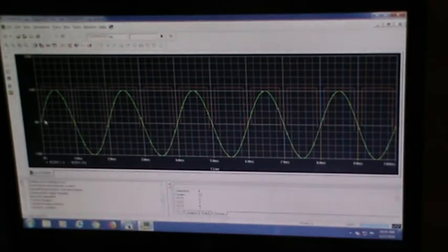See here, you are getting a square wave from +3 till here, more than 3 until less than 3. Till there you will be getting a square wave, and the rest all will be zeros. You will be getting a zero value for greater than -3 and less than 3. I repeat once again, you will be getting the output as 0 for greater than -3 and less than 3 volts. So this is called a window comparator.